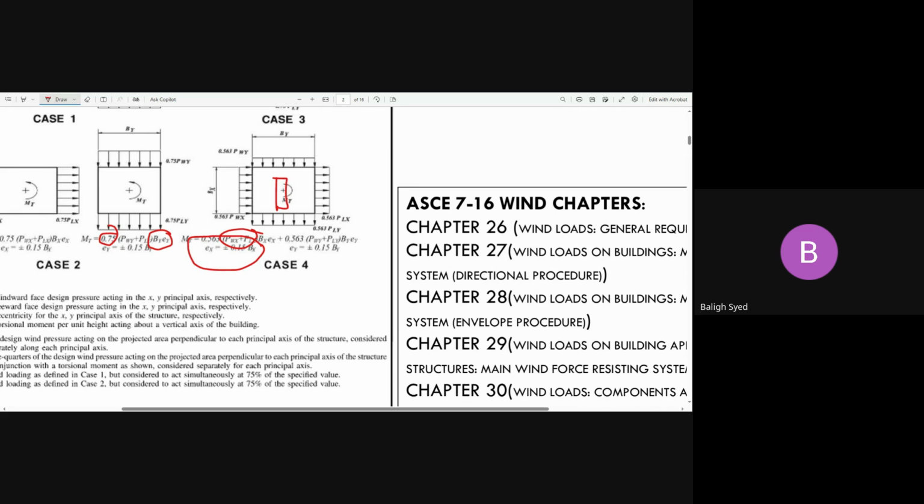But the primary difference which I keep telling you, always remember, on the flexible diaphragm there is no torsion load, on the rigid diaphragm there is torsion load. But even in the rigid diaphragm, usually in townhome projects you don't apply it, usually around 25 feet, 30 feet or 35 feet steel buildings you don't apply it, or even 30 to 40 feet concrete buildings, tilt wall buildings you don't apply it, right?